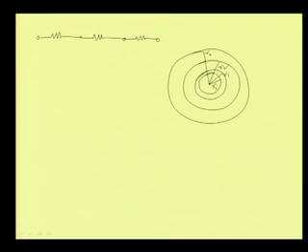So, if we say that the temperature at R I is T I, and then the resistance is this one, say R 1, then the junction between R 1 and R 2 is at temperature T 1, and R 2 is the resistance belonging between R 1 and R 2. Then at this junction the temperature is T 2, and we have another resistance, R 3, between R 2 and R 0 in this region. And finally we have T O, the outside temperature of the composite. Under that situation, what is R 1?